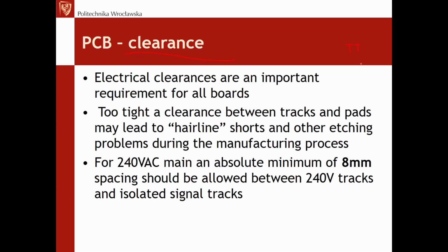Of course, on one side it is limited by the technology that we possess, technology that is available from the manufacturer. And you remember it was 0.25, 0.2 millimeter, even 0.15. But the clearance is also limited on the other side by the voltages, or the potential of the tracks.